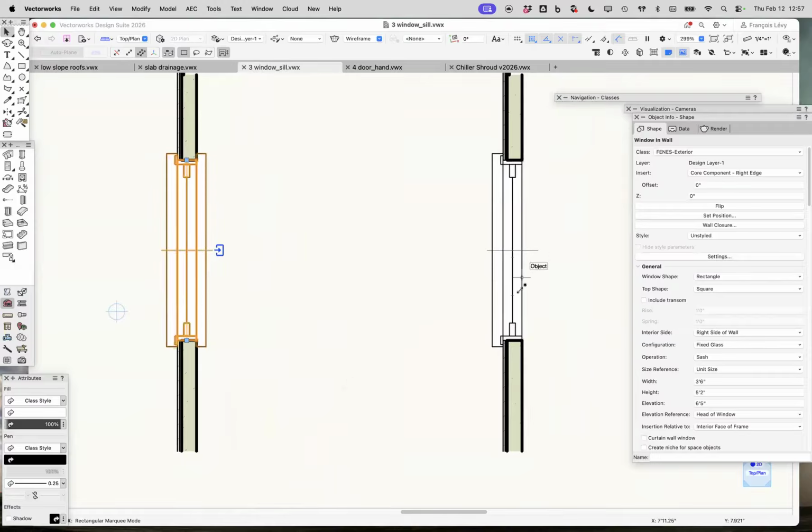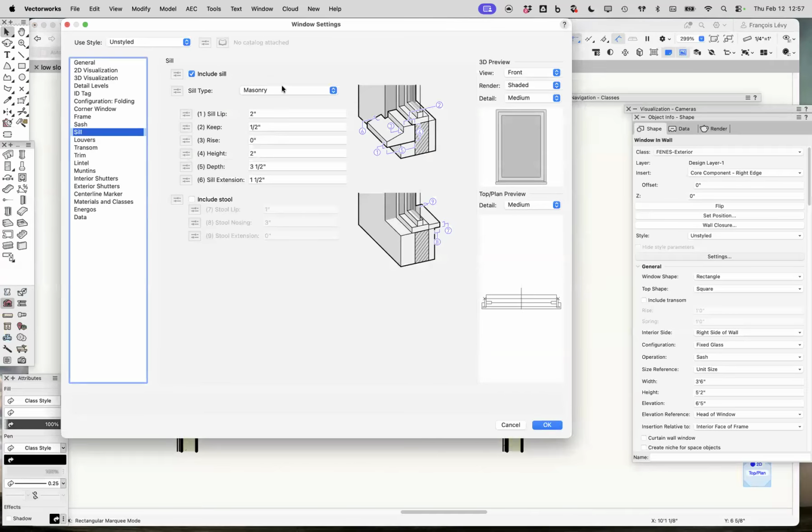In the meantime, the workaround that I've found is that instead of creating a timber sill or a wooden sill, which, as you can see in this diagram, extends underneath the sash, somehow the bug forces that sill to continue to extend to the inside of the wall.